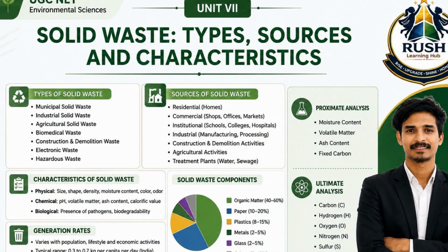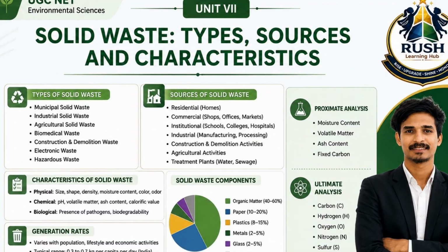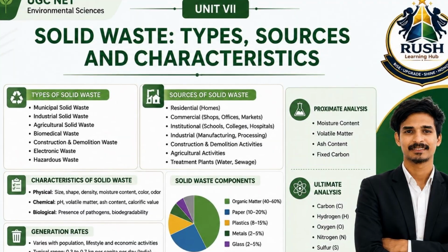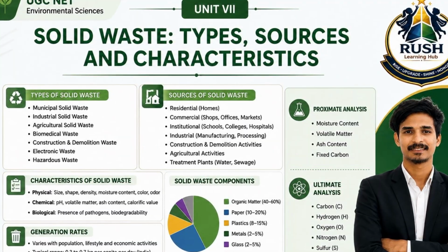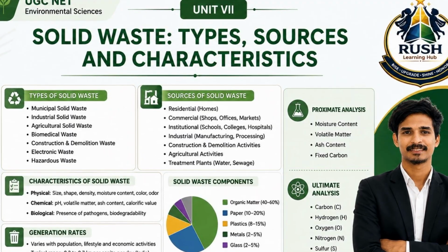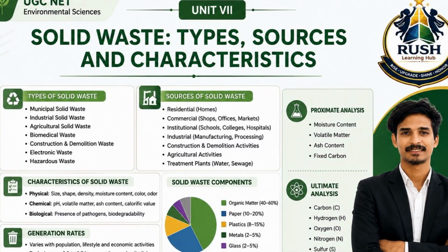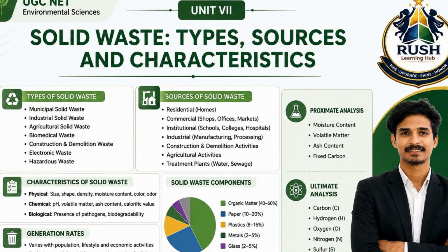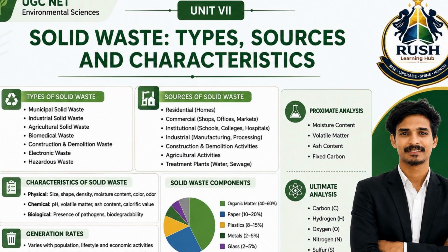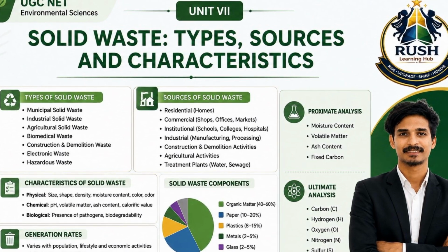Now let us study two very important analyses frequently asked in the UGC NET examination: proximate analysis and ultimate analysis. Proximate analysis determines four important components of waste: moisture content, volatile matter, ash content, and fixed carbon. This analysis helps evaluate combustion characteristics and energy recovery potential.